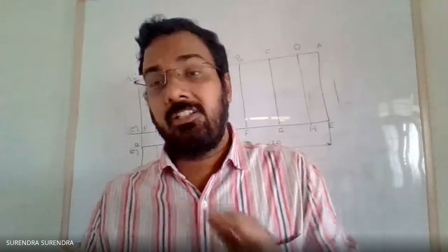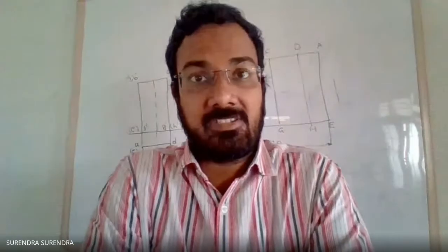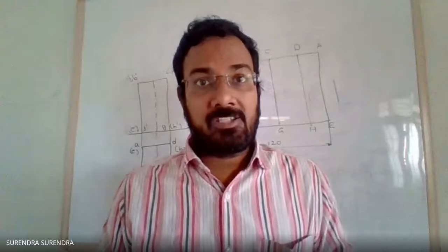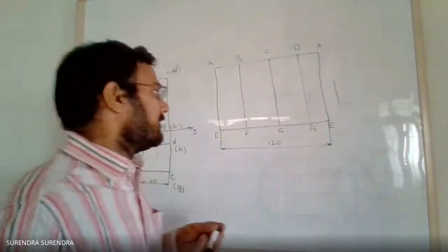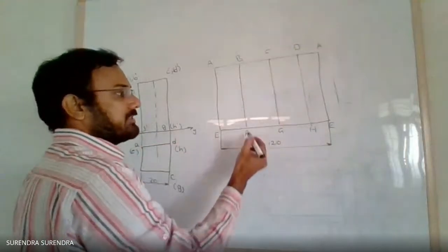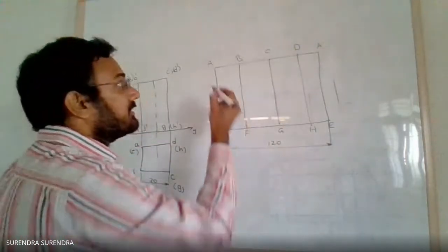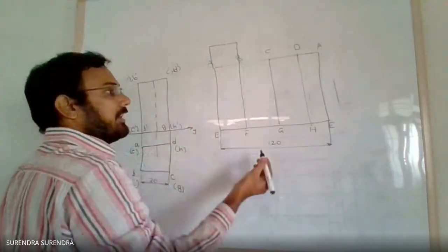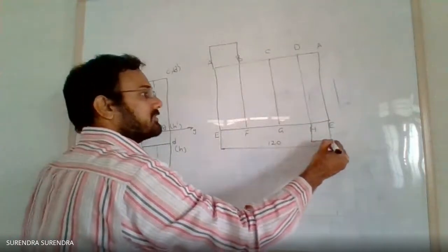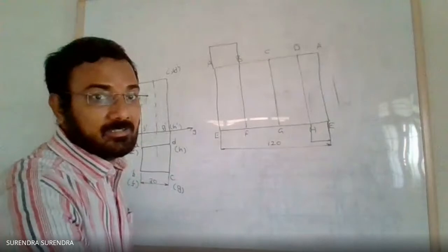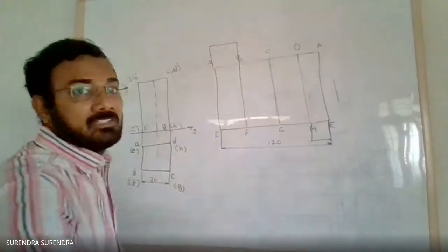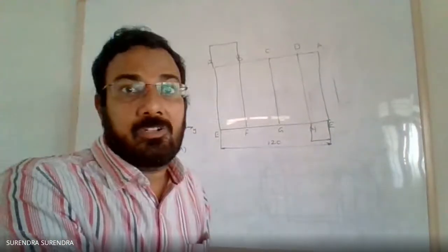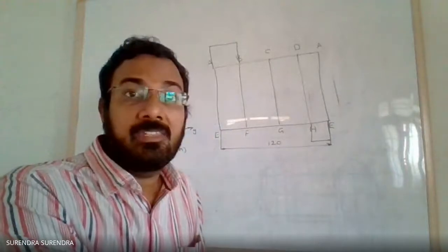Yes, top is there. Generally in the problem, they clearly mention develop the lateral surfaces. No need to draw the top base and bottom base. If they are given otherwise, you have to draw the top base and bottom base at any one edge. At one edge the top base and on one more side the bottom base. Two squares are represented on two sides, as it is AB, CD. Similarly, EFGH. Fully completed. Suppose if they ask you to also draw the base.